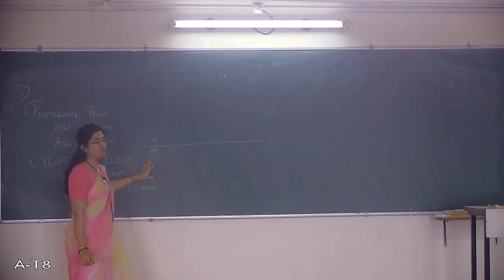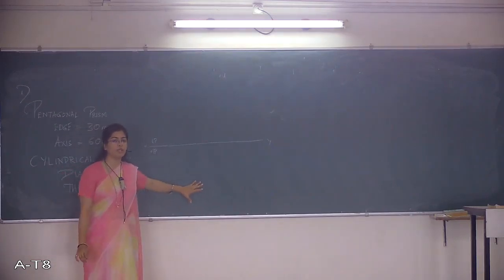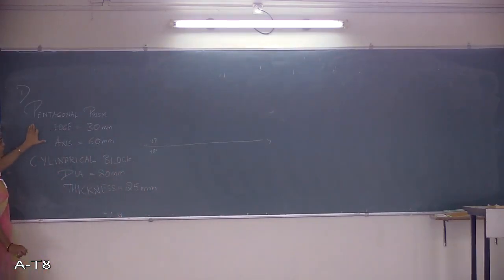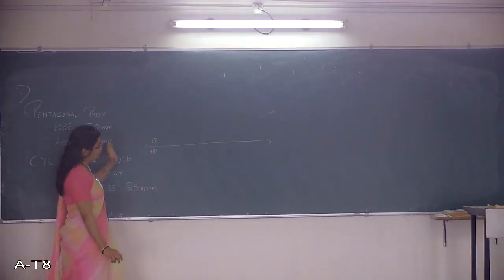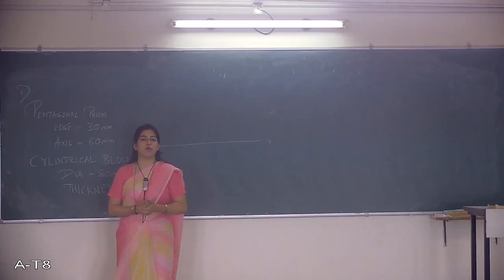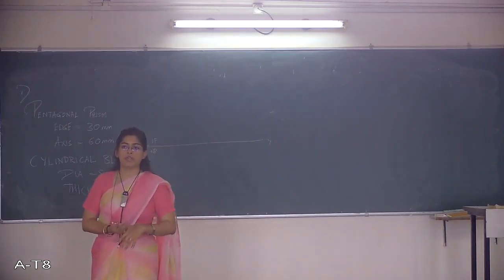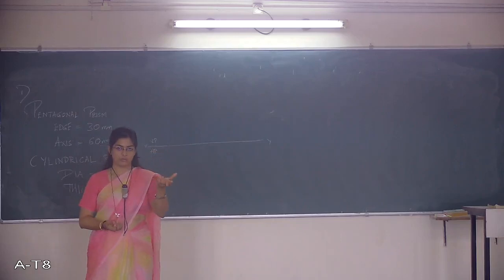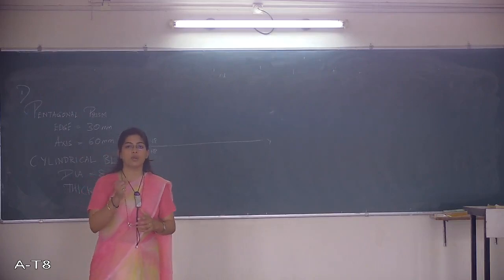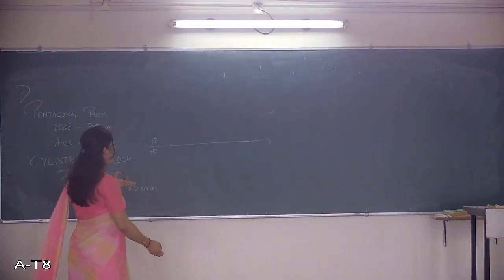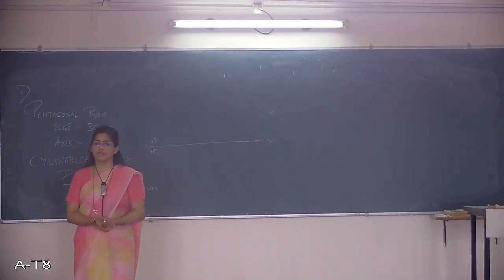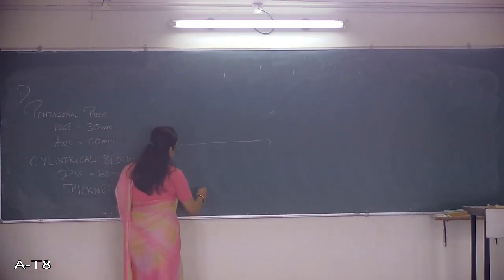As I said, first we have to get the orthographic views, that is the front and the top view of this combination of solids. So to start with, I have a pentagonal prism. This is what I am going to draw first. Now, as we have observed in planes or solids, when it was said that the solid was resting on its edge or on a corner, we used to place the pentagon accordingly. But in this problem statement, nothing like that is specified, so you can rest the pentagon the way you want. So I'll be resting it like this.